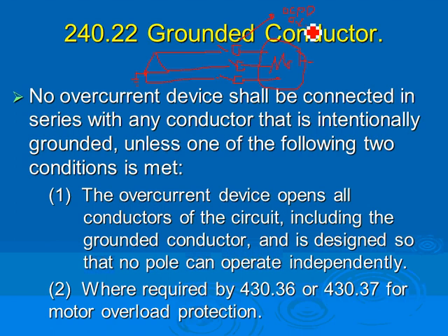Is that grounded conductor considered a neutral or a phase? No, it's not a neutral, it's a grounded conductor. Grounded phase conductor. A grounded conductor. That's corner grounded delta. Anybody dealt with corner grounded delta? That's when you have a delta and it's causing a lot of transients in your system. You will stabilize that delta. The cheapest way to stabilize it is to ground one corner.